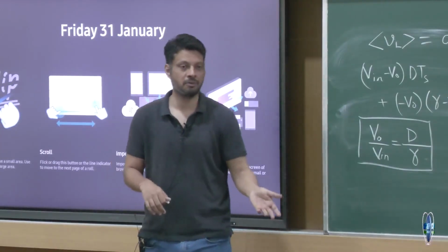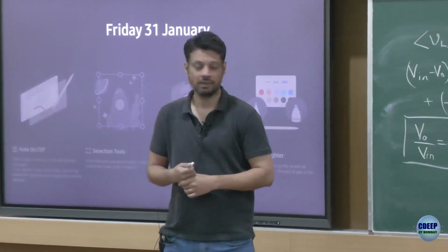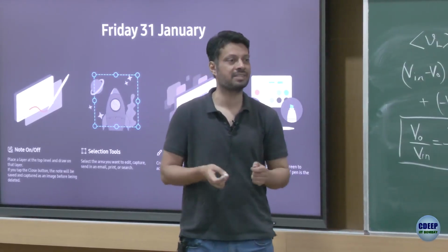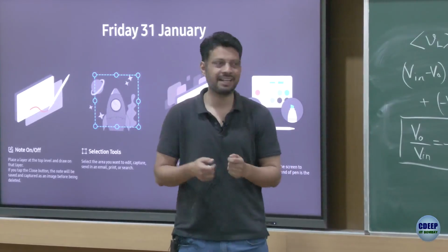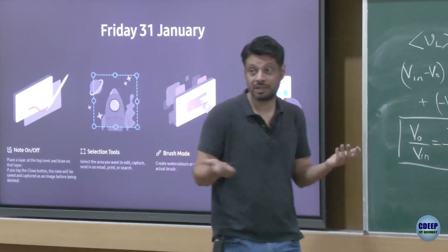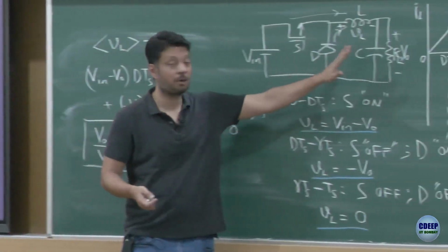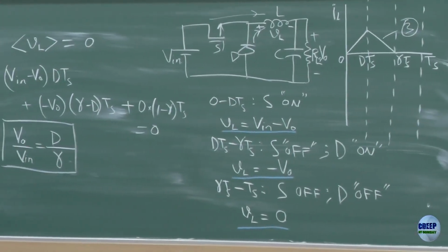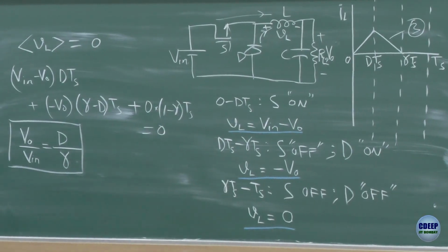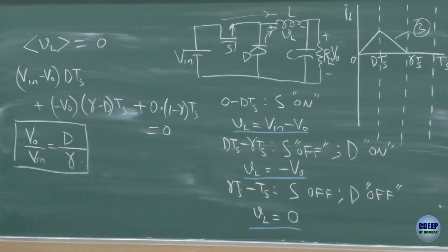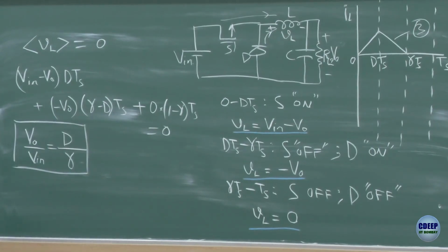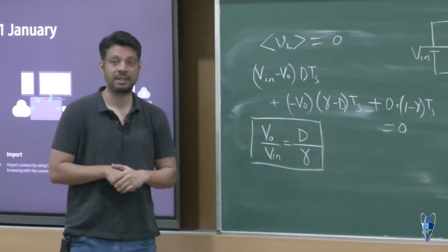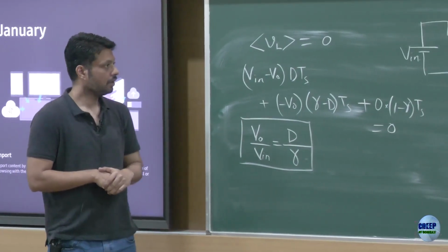In any application you pick, there would be a closed loop system to control these power electronic converters. Very rarely, you would have systems where there is no closed loop, very, very rarely. But you can figure out that in those systems, you must operate always in CCM first of all, because as soon as you go into DCM, there is a huge correlation between the load and the output voltage, right. But those are very, very rare systems. Most of the practical systems are to be operated in closed loop.